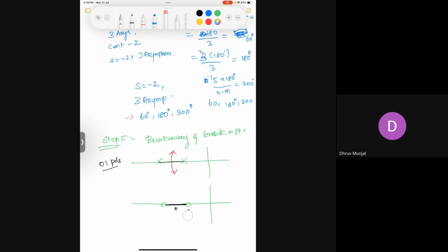So if there exists a root locus in between two adjacent open loop zeros, then the point in between will act as a break-in point, not breakaway. This is break-in, both point towards the same direction, it won't go out. I mean to tell that at least one breaking point will exist. Here also, at least one breakaway. It can be two or more, but at least one is evident here.